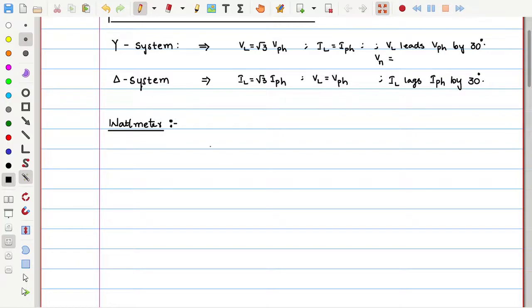Okay. So the schematic diagram of the wattmeter looks like this. It contains mainly two coils, where one coil is made of very thick wire, as like this. You can observe here I am intentionally making it thick with fewer turns. So this coil is made with fewer turns but thick wire. And one more coil is made with very fine, thin wire but more number of turns.